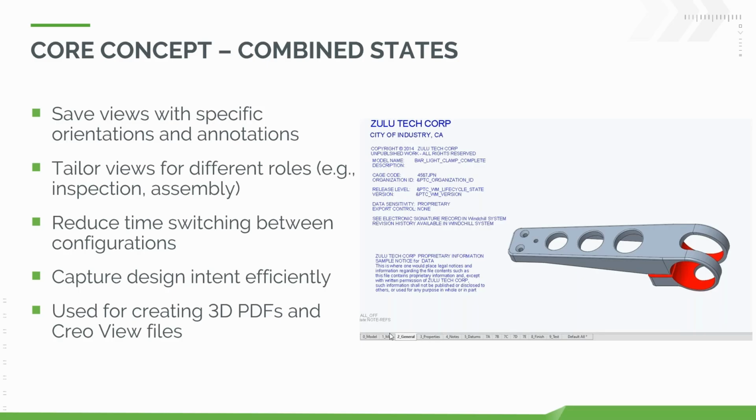Effectively, they become tabs inside of the 3D model, and you'll see later as I go through this, you'll be able to see different things and bits and pieces showing on all these different tabs. These tabs effectively are either like views in a 2D drawing, or they're like sheets within a 2D drawing. Sometimes you run out of room on one sheet, you move to the next sheet to show the view. Well, there's no necessarily concept of different pages here, or different sheets, but there is a concept of effectively as many different views that we like.